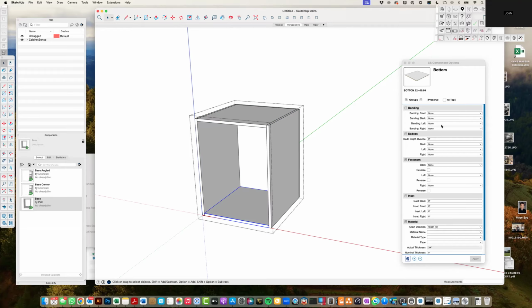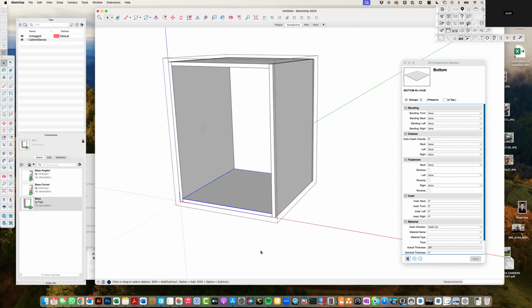So normally with this assembly method, we are cutting dados along the top and bottom edges of the side panels, just a 1/4 inch deep, ripping it with a dado stack and a table saw, and then using that for aligning the tops and bottoms. We then kind of glue and staple it, obviously. All right, gotcha.